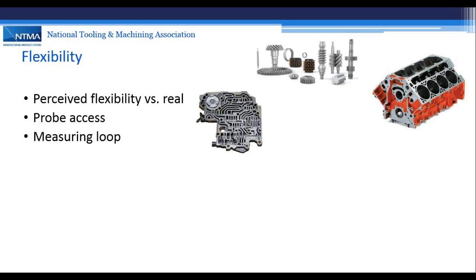When we start to look at the more flexible gauge with a measuring loop, at this point now we're looking at maybe 3 moving axis, multiple axis in the probe head itself, analytical calculations that are relative to 3D. So the measuring loop has to be, by basic metrology, the shortest possible to reduce uncertainty. Sure. But there's a little bit of a give and take with what's flexible and what's dedicated and what's achievable with the shortest measurement loop based on what's required.